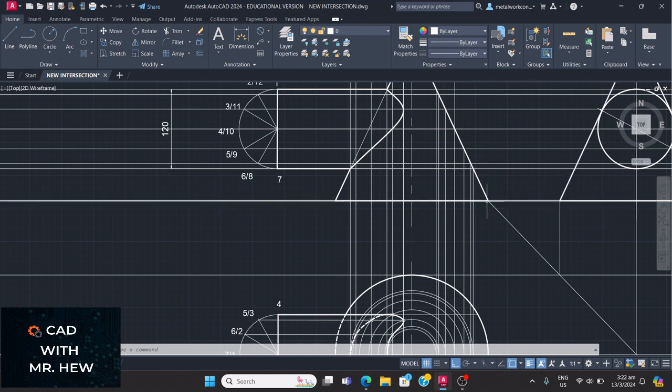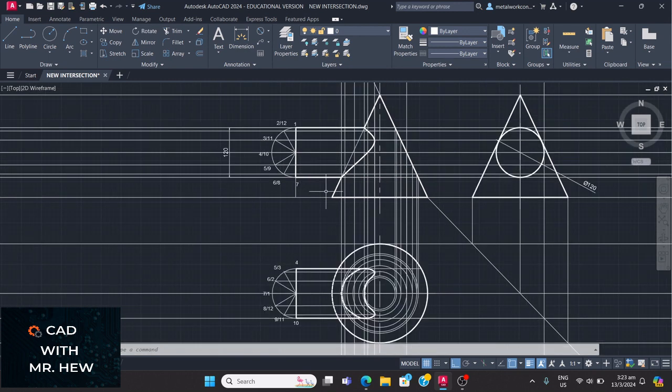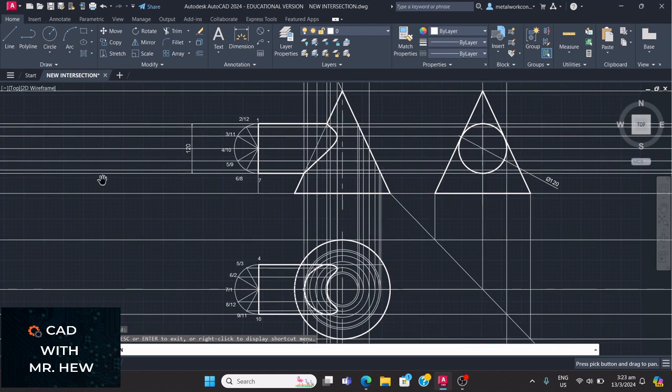And the space between here is wide enough to be beyond this construction semicircle. So I'm gonna drop a line from here to there, and that is where the 45 would be, if it was drawn with a T-square, okay? But what you do, you look at the drawing, and what I want is the other end elevation on the left of the front elevation. So in AutoCAD, can I guess what command you're going to use to get it over there?